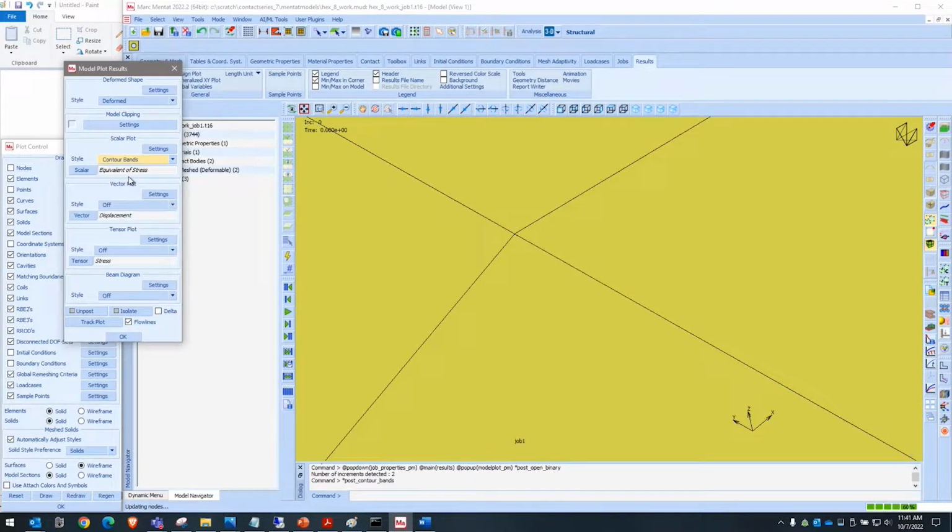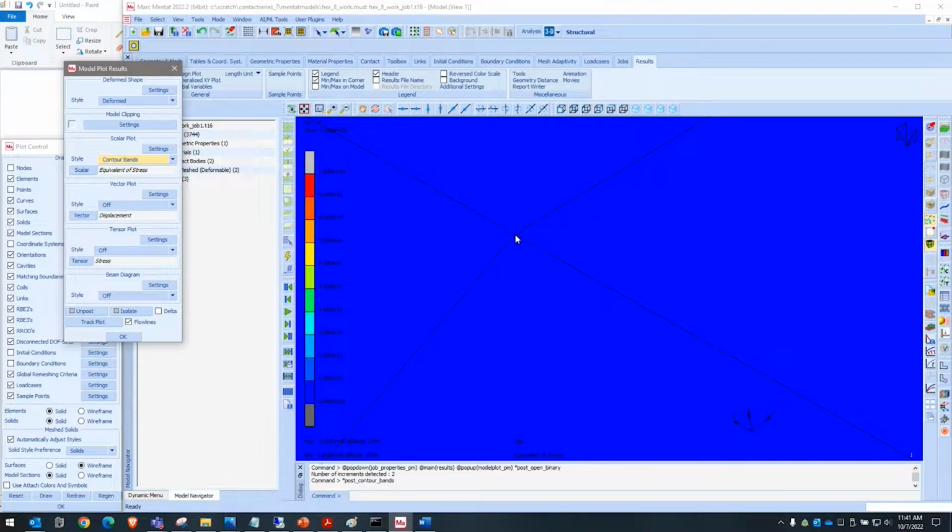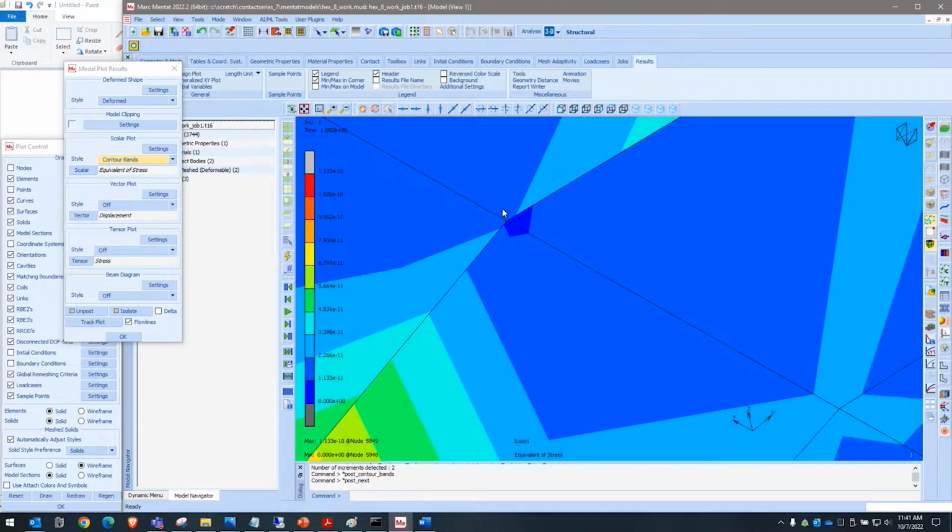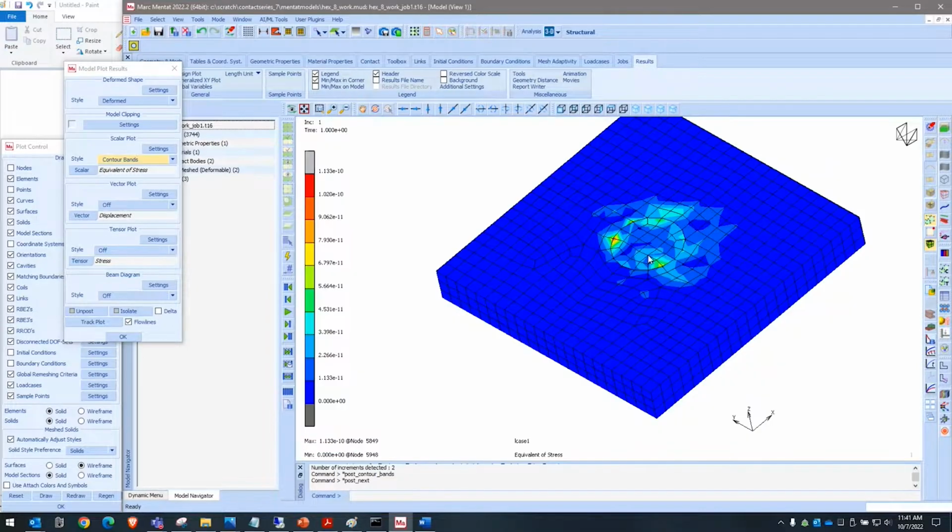Okay, and look at the stress. So there you can see it's projected. And if I look at the stress state, again, that's pretty much zero. If I look at the numbers, it's something E minus 10. So it's even lower than before. So it's a really, really low stress. Okay, so the project stress free work, but now I've lost my interference fit.